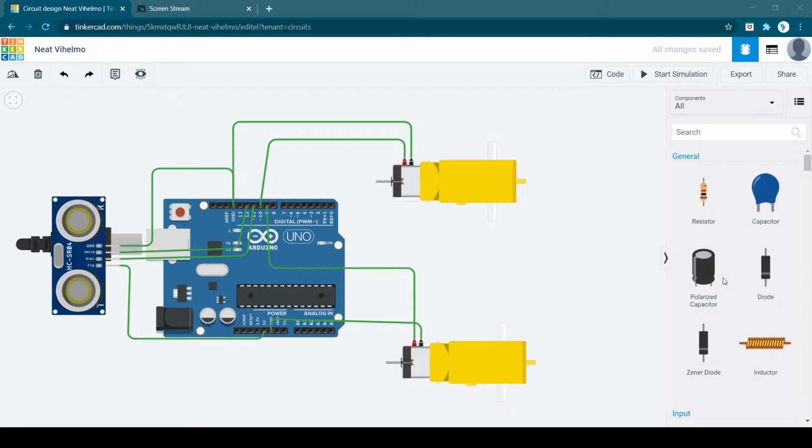What you need to do is check the distance. If the distance is more than 50 centimeters, then rotate the motors clockwise, and if the distance is less than 50 centimeters, then rotate the motors anti-clockwise. And here you have a very great challenge for everyone. If you have understood it properly, if you remember all the classes properly, you have a great challenge here. It's a pretty simple logic behind all these things.